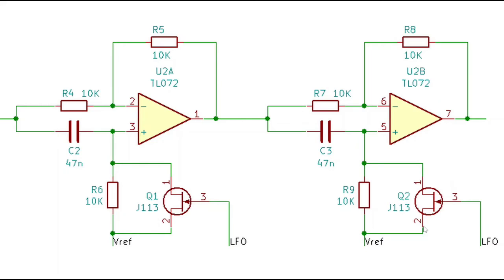Here, it will get the value up and down, and this voltage between gate and source would be affected. So as we go down, we are increasing this. The difference is going to be negative, because this is at a lower voltage than this, so we're going to drop this until we are nearly in cutoff.